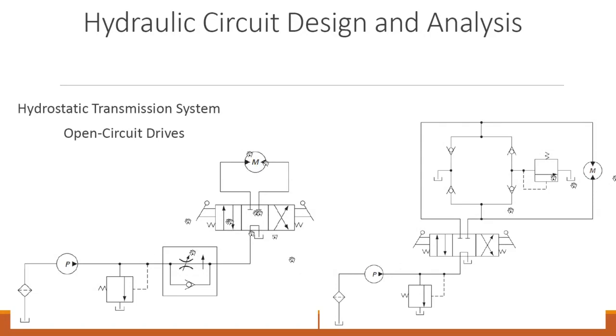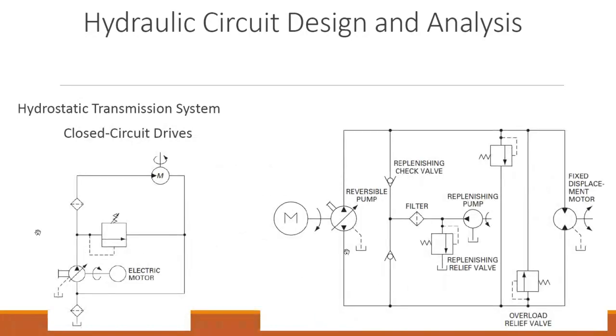So if I ask you in the exam and show you, for example, this circuit, whether it is an open circuit or closed circuit, you see that as soon as the oil goes to the tank, it is an open circuit. Everywhere you see it's going back to the tank or the reservoir, and then the pump takes it again from the same reservoir. So that is the open circuit.